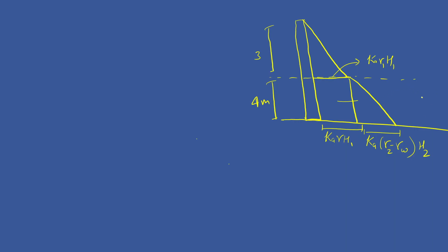And then you also have the water table available here, so this will provide the required hydrostatic force, and this will have the value gamma w into h2. Okay, so these are the maximum stresses which will act on the retaining wall from the soil medium as well as the water.